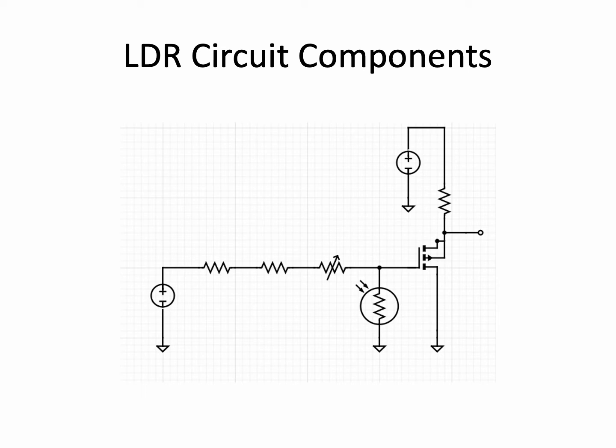The behavior of the FET is controlled by a voltage divider on its gate, composed of 2 resistors, a potentiometer, and a photoresistor that decreases in resistance when exposed to light. These components are arranged in a voltage divider configuration on the gate of the transistor. When a laser beam is cut by the player's hand or the paddle, the reflected light incident on the photoresistor causes a drop in voltage at the gate of the transistor, placing the MOSFET into cutoff.